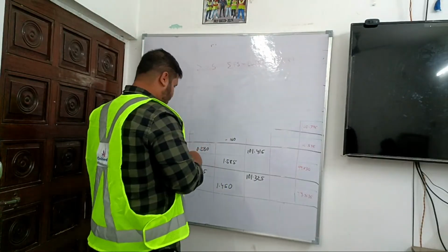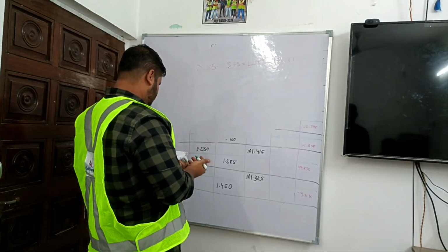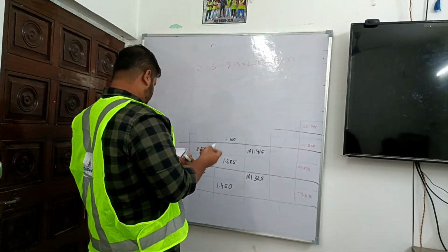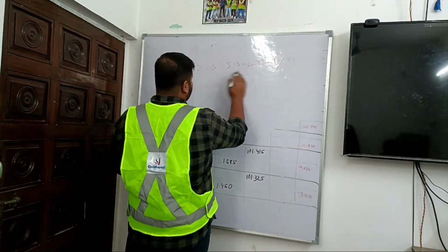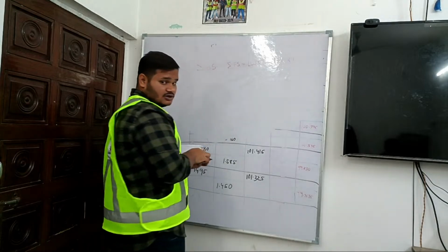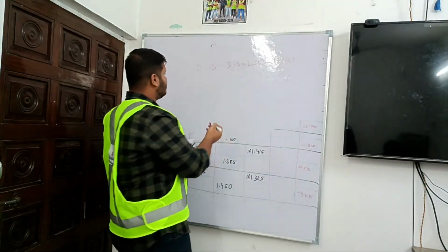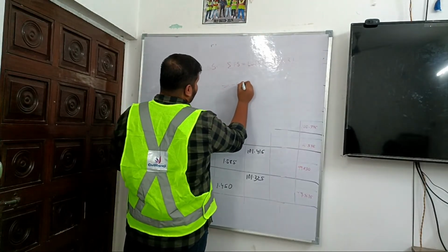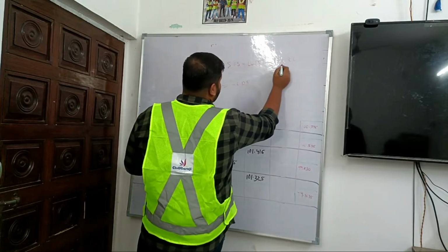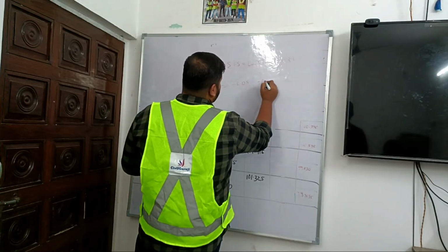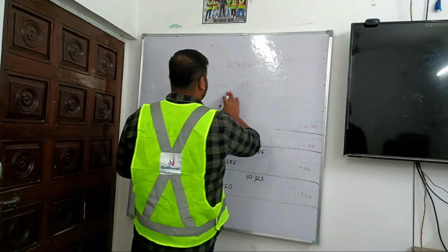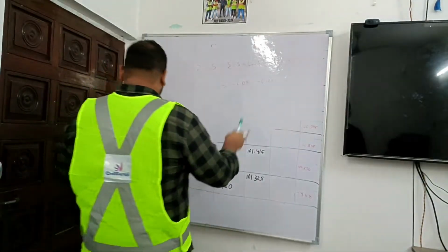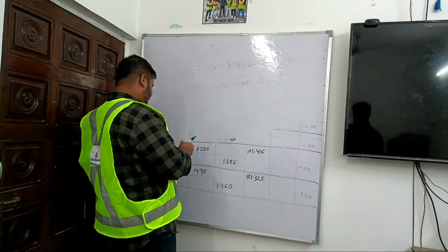So in this case, what we saw in the table, the error was minus 0.125, and here also last RL minus first RL comes out to be minus 0.125. Now this value has to be distributed in the RL values, which will give us a corrected RL value.